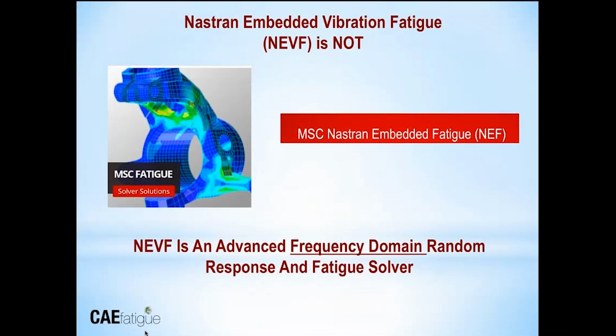So Nastran embedded vibration fatigue, I'm going to talk specifically now about that. I'll start by telling you what it isn't. It isn't MSC fatigue. MSC fatigue is a Patran-based fatigue tool set that sits inside the Patran GUI. It's also not MSC Nastran embedded fatigue, which is a time-based embedded solver that is already inside the MSC Nastran product. Nastran embedded vibration fatigue is an advanced frequency domain random response and fatigue solver. So the difference is between NEF and NEVF. NEVF is a frequency domain solver. So that's really what I'm focused on today.